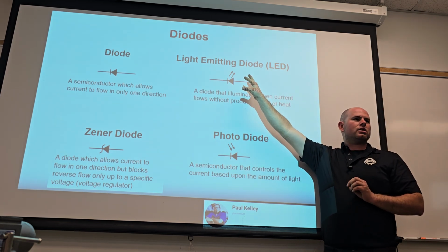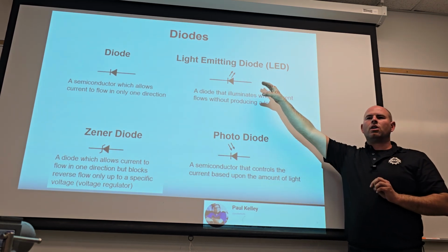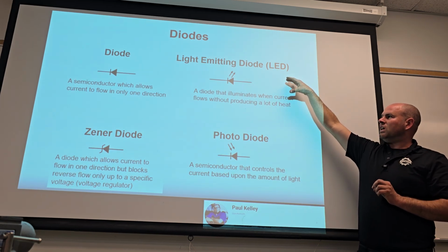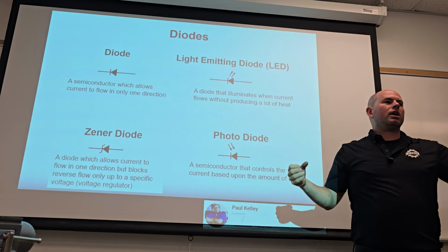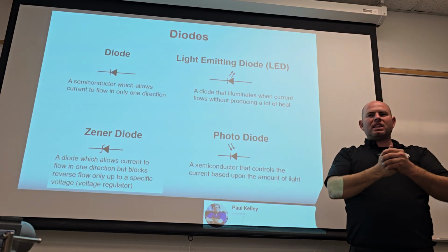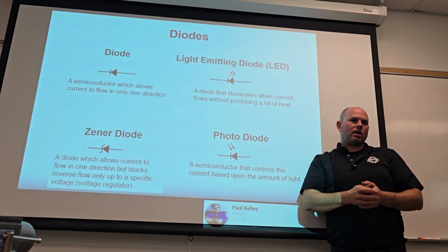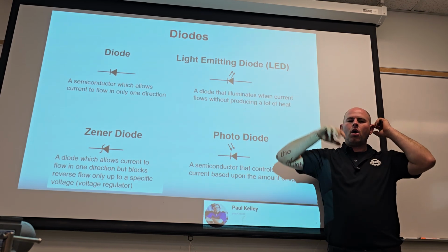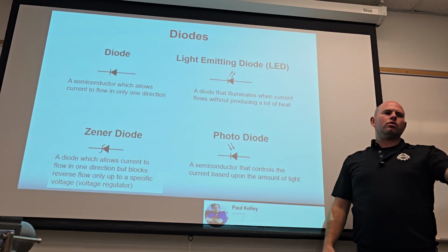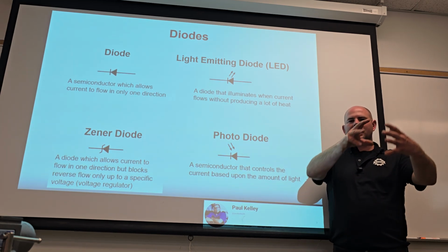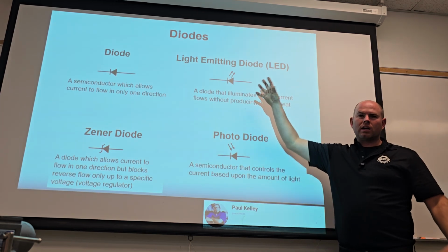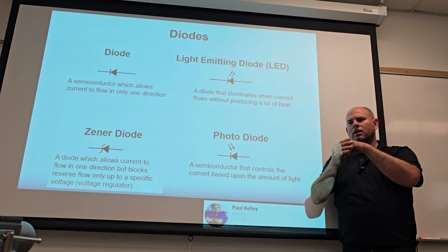So this is just the way that the business has gone. If an LED is bad, you can't just unplug it and plug a bulb in. And being that I just explained to you, they can be expensive, you have to be able to diagnose this. You can't be like, oh, your taillight's out, let's get a new $2,000 taillight and plug it in, see if it fixes it, because you can't take them out anymore. This is integrated into the housing. You plug it in and it gets a signal.